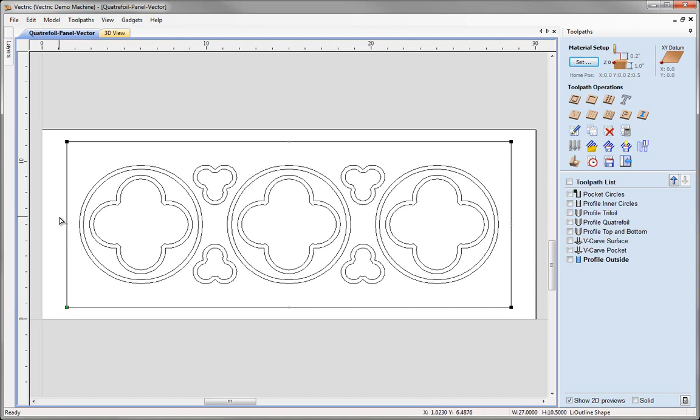Easiest way to do that would be to insert a point here. So I'm just going to click and drag to select my virtual midpoint there, right mouse click and say insert a point, or I. And then what I can do is change that to be the start point, and the shortcut key to do that for hover over the node is P on the keyboard to change that to start point. So that now is my new start point for this vector.